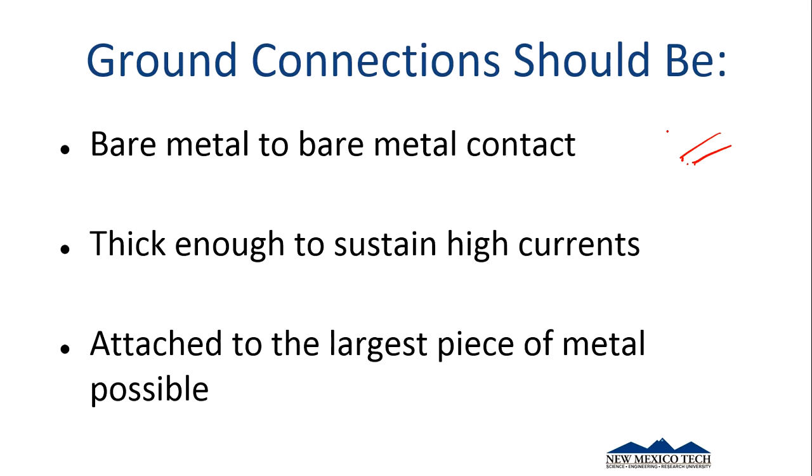I knew somebody who was working on electronics for the Navy, and they were doing some work on a helicopter. They couldn't figure out why some of the electronics in the helicopter weren't working, and it turns out they designed this whole system and installed it, but at some point somebody had painted the helicopter body, and whoever installed the electronics just bolted the ground strap right to the painted body, and it wasn't a good enough ground, and so it made for a scary flight when they tested that out. So really important to have that bare metal contact.